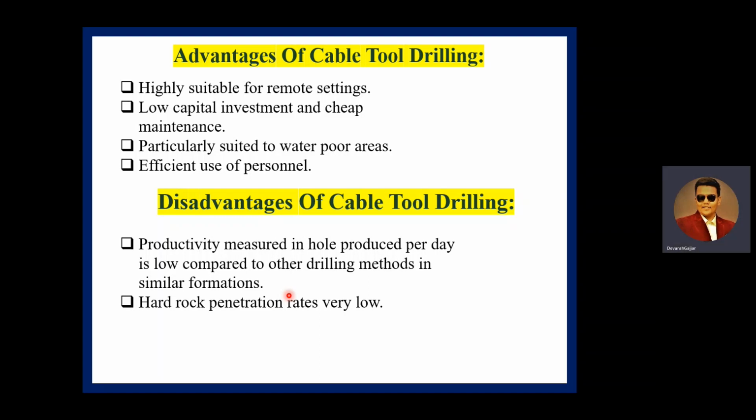As seen, in various types of conventional rig, there is top drive drilling, rotary drilling, and we need a circulating system, mud pumps, and an electrical system. But in cable tool drilling, it is not much required because it is a basic type of drilling based on the reciprocating motion of the drill bit to break the rock. And if the slurry fills the baler, it is removed out of the hole and emptied, and then the same procedure continues.